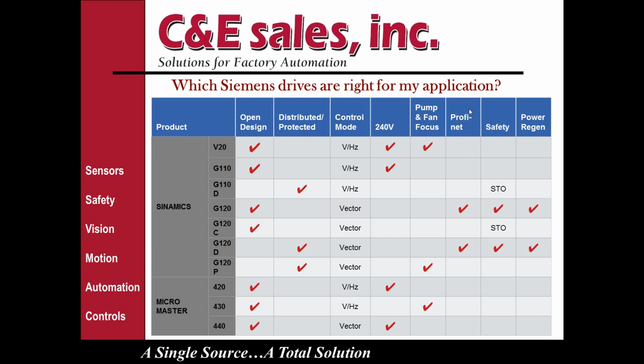Profinet and other bus structures are an important consideration when picking out a drive. Communications options are very broad in most of the drives from Siemens, but not in all. And that's an important distinction to take into consideration when you're looking at the drive for your particular application. We'll talk about some of those.